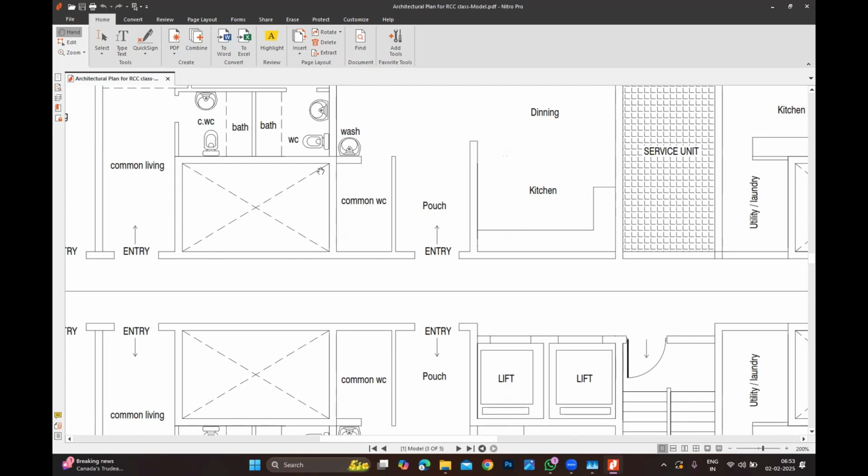If you see the A.E.X.L project, you don't have false ceiling. Except the toilet, there is no false ceiling. Not even in the kitchen. Usually, false ceiling will be in two places, right? Kitchen and toilet. In A.E.X.L, in most of the projects, you don't have false ceiling in the kitchen also. Only the small washroom. And how would you be able to cover those beams? Do you want to stop the beam only for 3 meters in the kitchen? My column is after 3 meters, then I need to continue the beam. I understand. No? Automatically, the beam will be exposed.